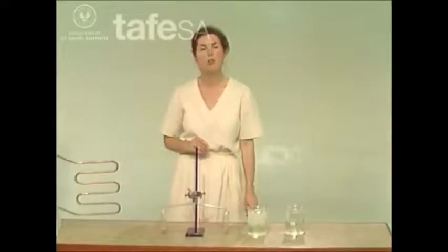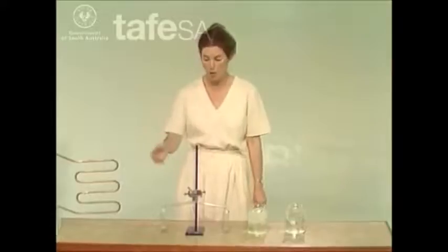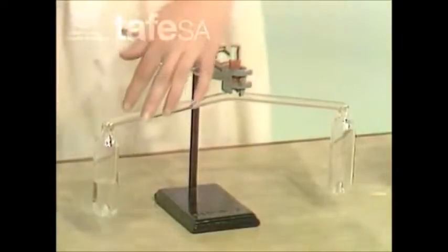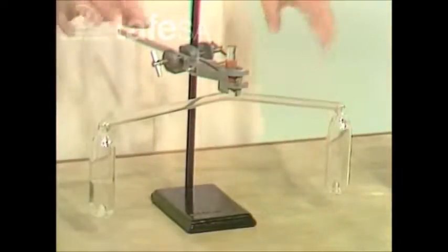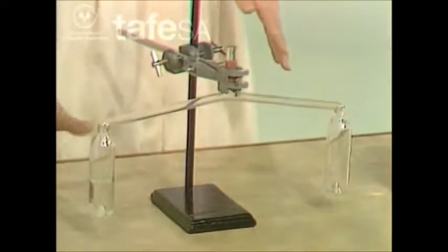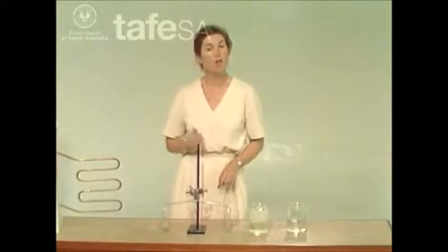This model shows how a refrigerant changes state, transferring heat in the form of latent heat as it does so. The refrigerant in this closed container has partially vaporized, and the vapor fills the tubing and the second container. The small amount of pressure in here acts on the refrigerant and prevents it boiling, even though the surrounding or ambient temperature would normally allow that to happen at atmospheric pressure.